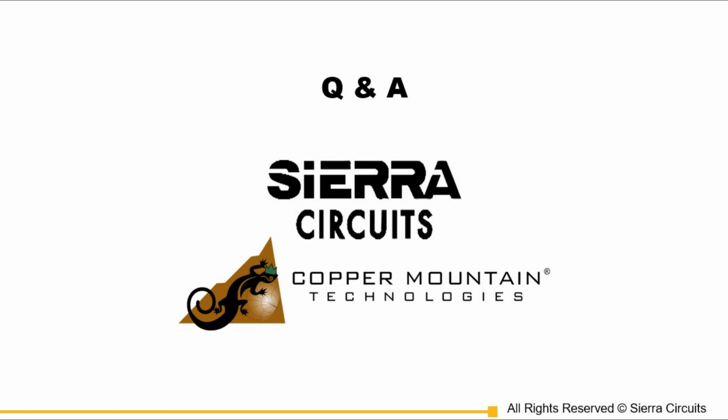The one thing it does not do, it does not correct or remove reflections. So if there are reflections between the primary reference plane and the point to where you moved it, those reflections are still there. So moving from the end of your cable, say through a pigtail to a circuit board, if the pigtail has a 10 dB return loss bump in it or a crimp, you'll probably get the phase sort of right at the circuit board, but the return loss will be terrible.